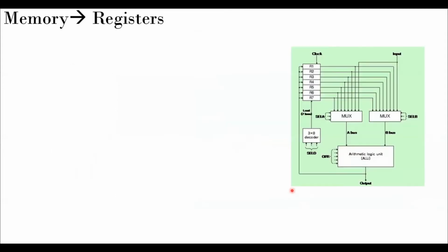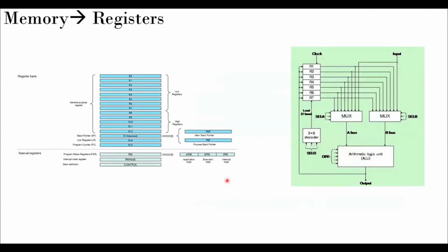Okay? So now registers, we already saw this sort of layout for our Cortex M0 Plus. So many general purpose registers, and then program counter, link register, and stack pointer. Some special status registers over here. So all these registers have direct connectivity to the CPU. So this is an illustrative figure. So we have the core here, the ALU here, and each of these registers are directly connected to the ALU. Okay, so this is your bus, for example. So this bus will come to the register, and the register will convey that data to the ALU. The result will also get stored in a register, and from the register it goes to the bus and to the memory, right? So that is the typical path.